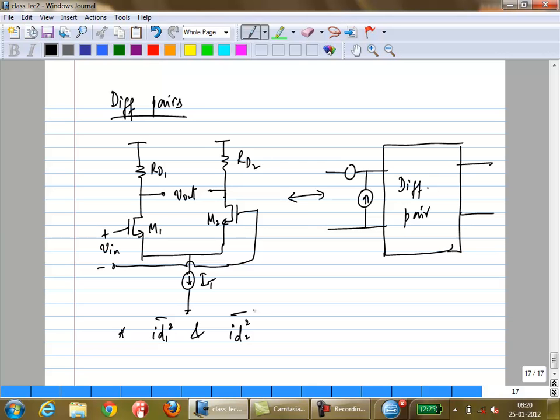In that case, it was completely correlated and negative. That's why you could break it up into the half circuit. Here, because it's uncorrelated, you can't break it up into a half circuit. You have to do a full analysis. You have to start by looking at each noise separately and then find out the input referred noise for each. Okay?